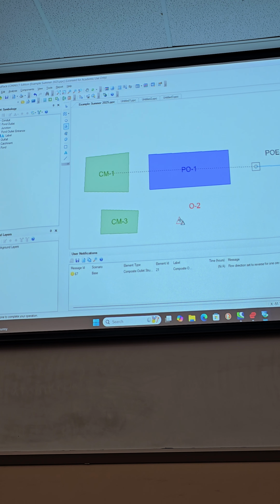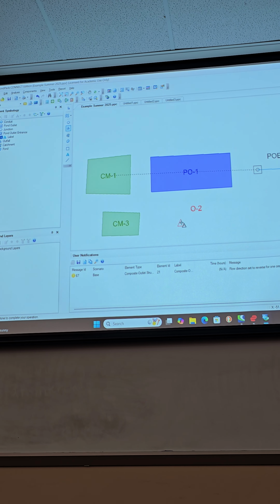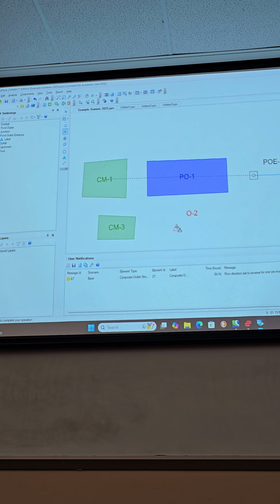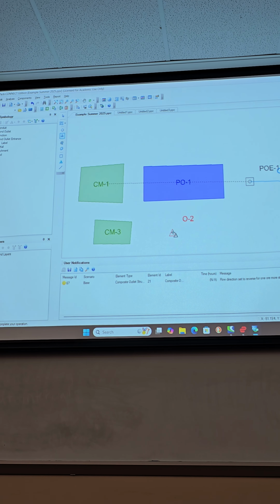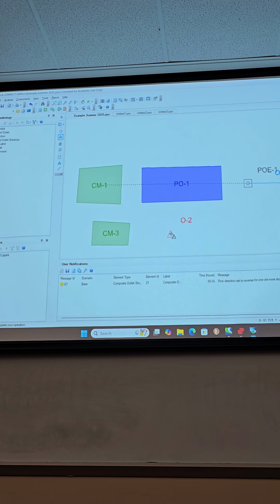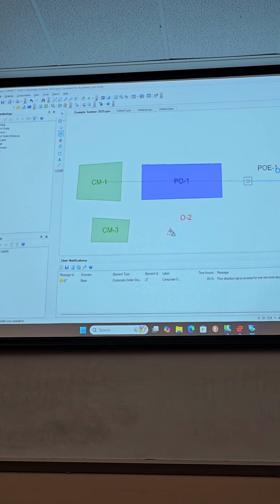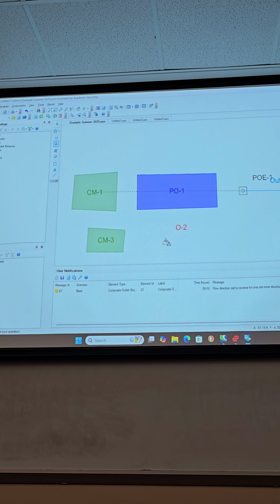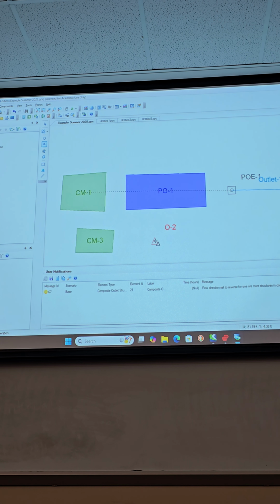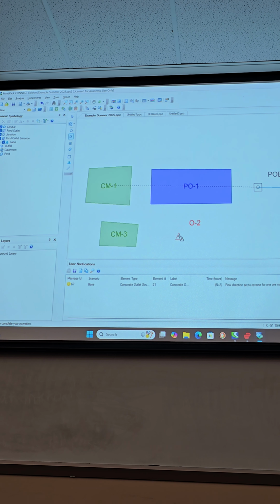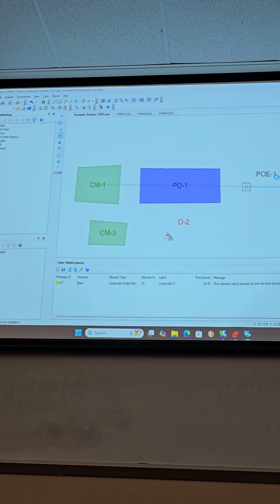In the pre-development condition, you're not routing it to a pond. You're just estimating the flow from your catchment or basin area. So if I connect the catchment directly to the outfall, I can do my pre-development in the same model. If I run it, I can see the post-development and pre-development on the same table, and very quickly assess, am I meeting this criteria? Okay?